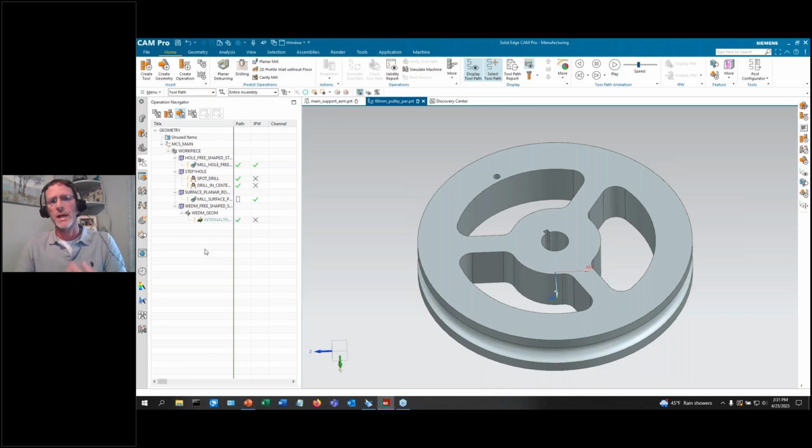Me personally, I use this even though I don't alter it out of the box, because for Saratech doing contract programming, it does me no good to bake in processes of one particular company. So I leave it out of the box, but I always start with it because it creates my whole groups and it gives me 80% of my program to where I only need to focus on contour machining or updating some of this information. Extremely powerful tool.